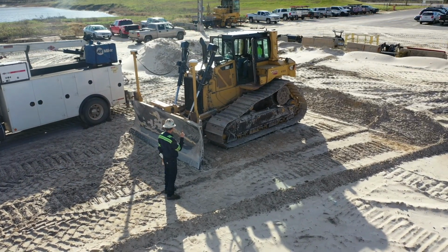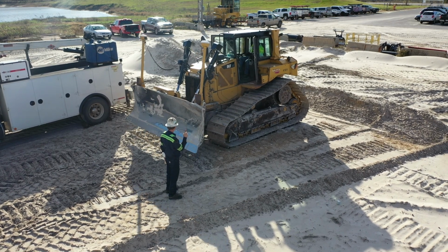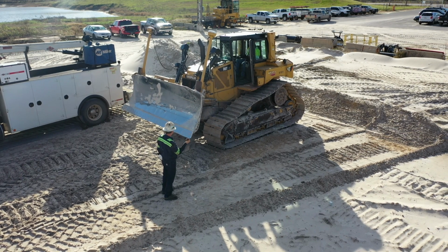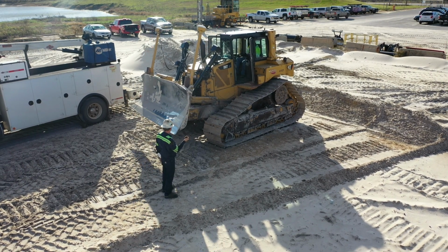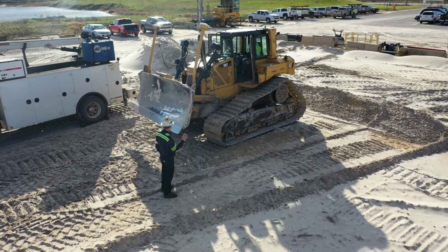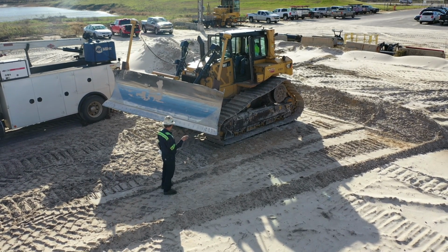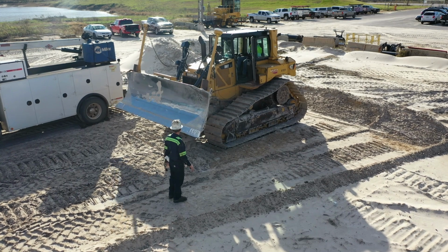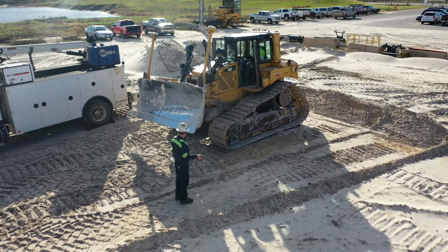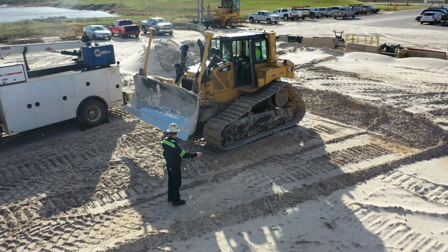Communications while assisting in mechanical repairs. When operators are assisting mechanics to repair machines, clear communications must be established prior to starting the tasks. The operator and the mechanic must each know who will be responsible for: A. Starting or moving a machine. B. Ensuring that anyone involved is in a clear and safe position. C. Directing the movement of the machine, and D. Ensuring that it is safe to resume working and that all guards are in place.